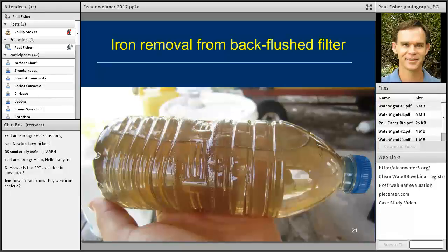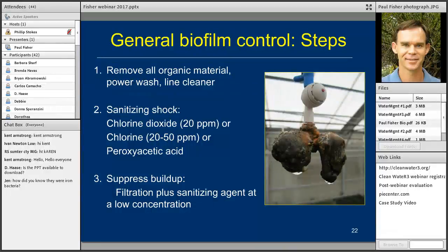We looked at the other aspects of the water test, the nutrient water test, and the other aspects of chemical water quality were good. We also knew that there was a high bacteria count, and if you looked at the type of slime that was accumulating in the drippers, it had that very typical orange, snotty look to it that's typical of iron bacteria. With manganese problems, often it's a darker, more of a gray or black color.